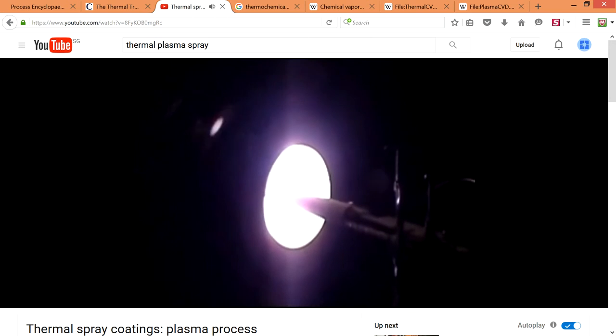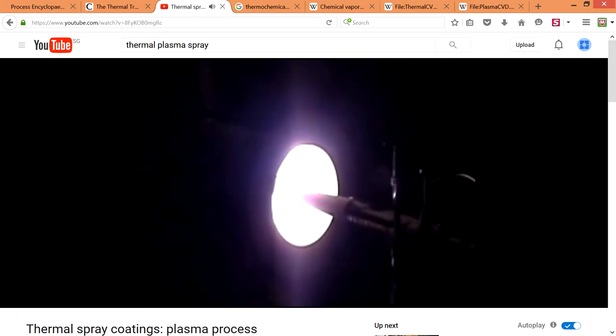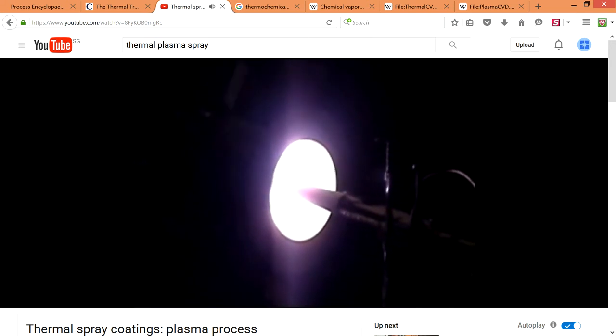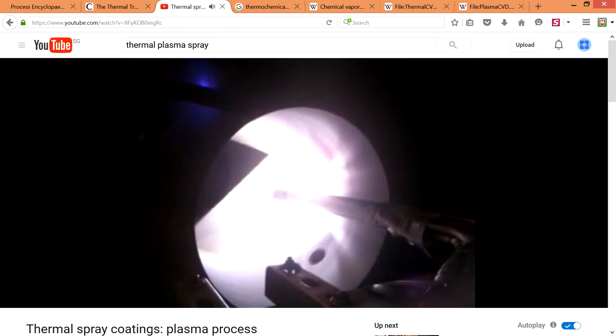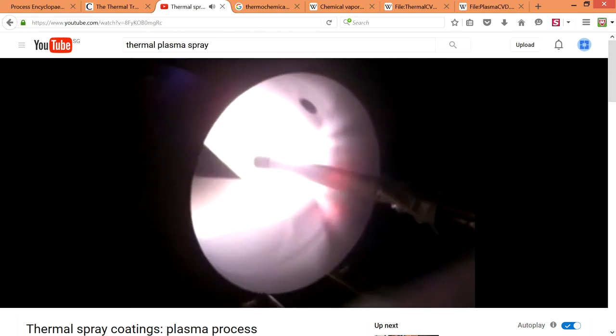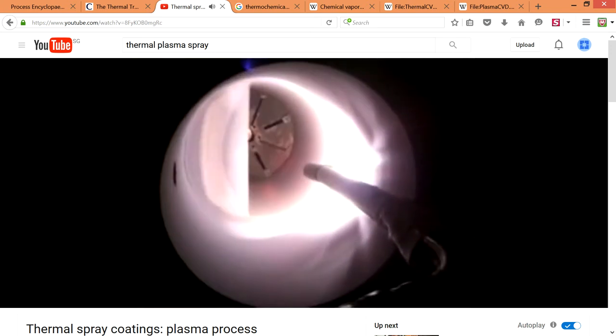Hard ceramics like chromium oxide, aluminum oxide, and titanium dioxide are extremely wear-resistant when plasma sprayed. Plasma coatings of yttrium stabilized zirconia and magnesium zirconate display terrific thermal barrier properties, excellent thermal shock resistance, high-temperature corrosion resistance, as well as resistance to the action of molten materials. Plasma coatings make good use of the extreme temperatures of ionized gases, making it the perfect process for coating components with high melting points such as ceramic materials. The process brings out the most useful properties of ceramic coatings, from very high hardness and wear properties to exceptional thermal barrier and high temperature stability capabilities.